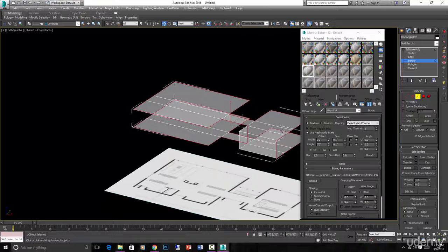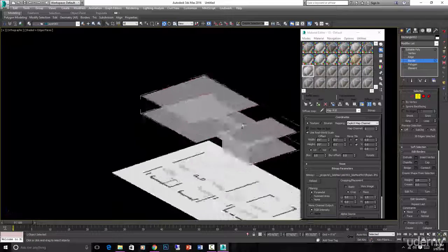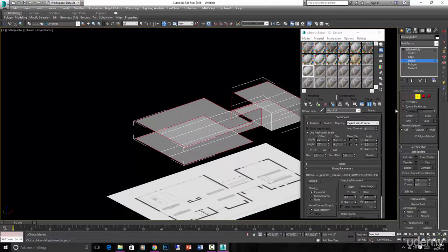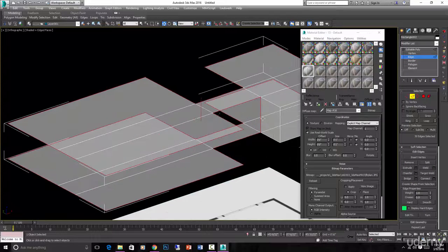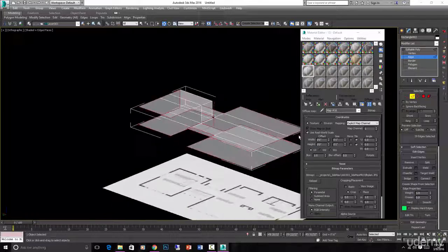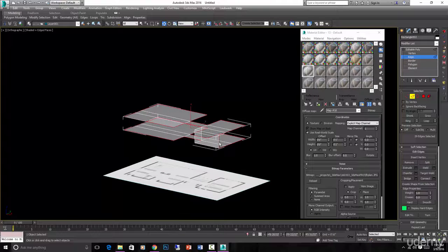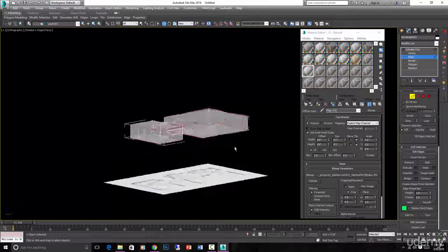Now, if you select border, you see it'll go down this way, which we don't want. I'm going to try and bridge all this at one time, so let's hold down Control and go into Edges. So now it's actually in edge mode, but the same edges remain selected from the border mode. And just hold down Alt and unselect that one. So now we have all the edges we want to bridge and no extra ones. Except for this one right here. Now if you hit bridge, it'll bridge them all at the same time. Boom.